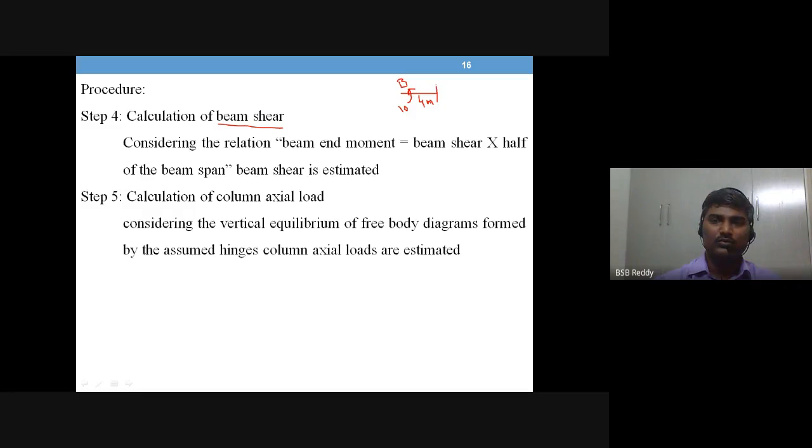So now this is your shear. Okay, so you know the end moment as 10, and what is this force that will give you 10 at this point? So to get moment at B as 10, what force should be here? It is simple. So V in BC, that means shear in beam BC, into 4 is equal to 10, right?